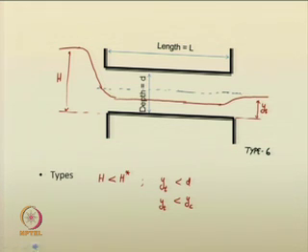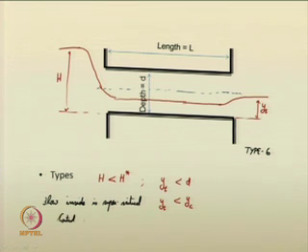Flow inside the culvert is supercritical. So, if you want to provide supercritical flow inside the culvert, the control is kept upstream. Okay, here if you provide a control in this portion, you will get the supercritical flow inside the barrel.